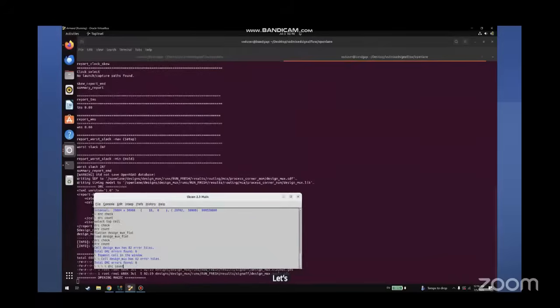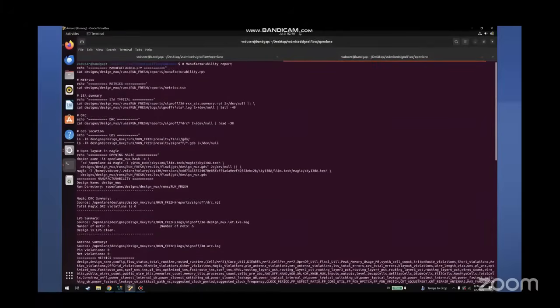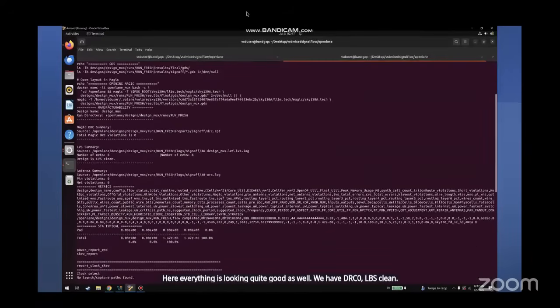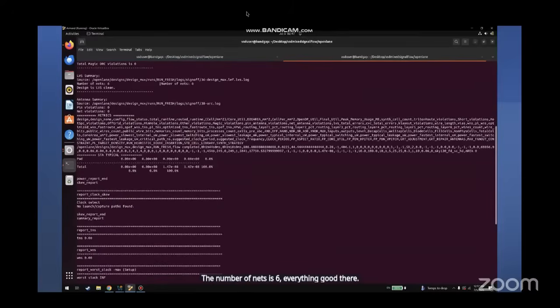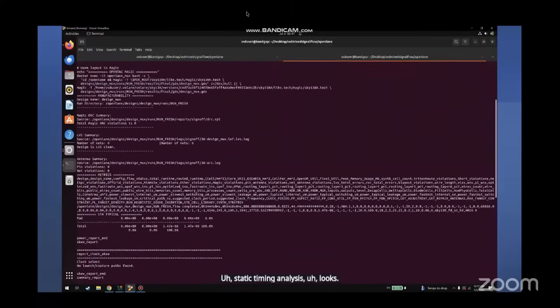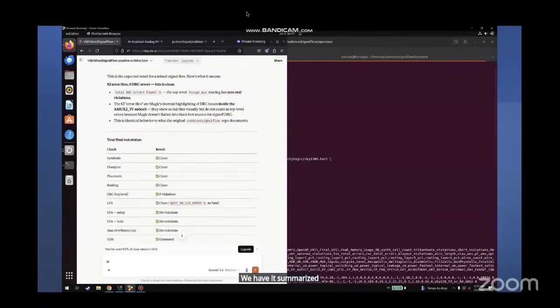Let's go to the manufacturing summary. Here everything is looking quite good as well. We have DRC 0, LVS clean, the number of nets is 6, everything good there. Static timing analysis looks pretty good as well. We have it summarized here.